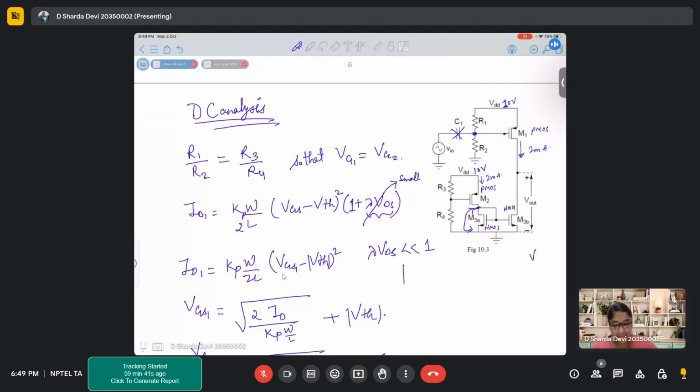So that's why you must have seen that we never used any other current equation, right? Because if we had linear transistors, the current equations would change, but we never used that. We always use the saturation current equation. That is because for amplification operation, your transistors must be in saturation. So that's why. Okay, hope this is clear.